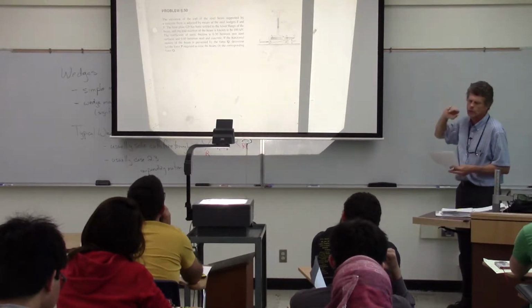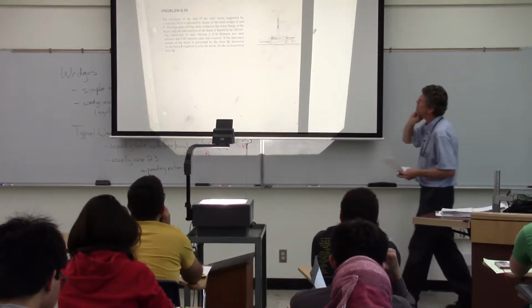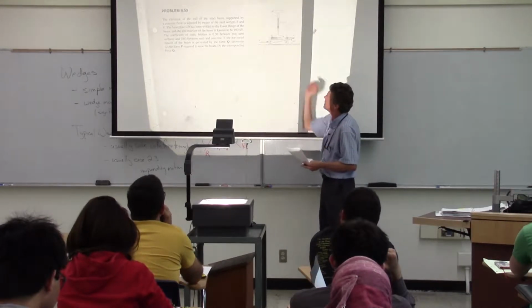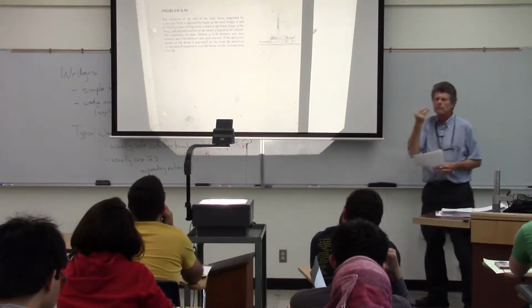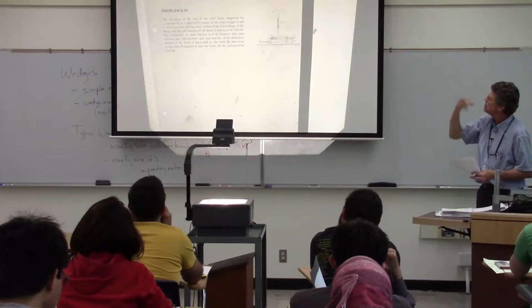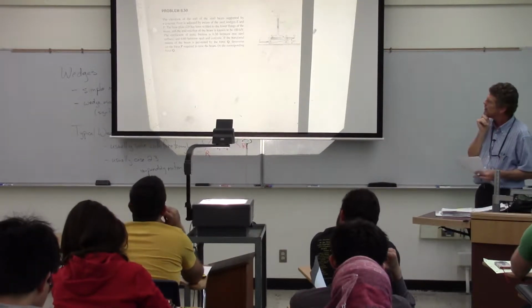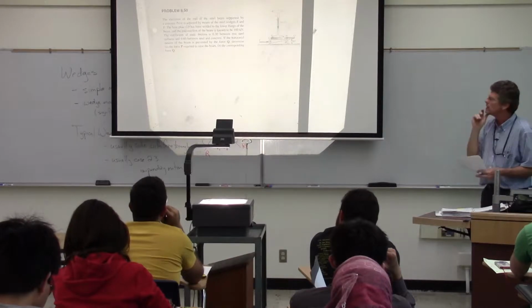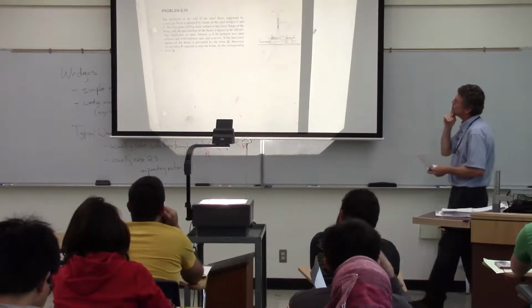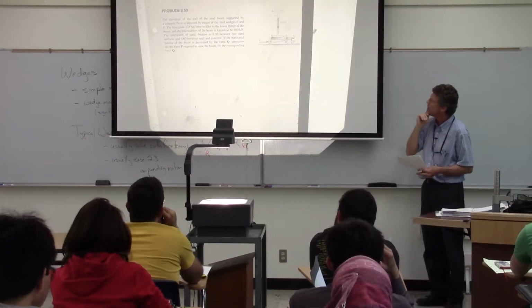And if F shoots off, then it kind of shoots our purpose there, and we probably have to apply some sort of force there. So again, when you think about wedges, you need to sit back and look at, okay, what's moving, what's not, what's got friction, what doesn't have it. And oftentimes, like in the EIT exams, they'll give you different surfaces with different friction coefficients, so you have to be careful there too.